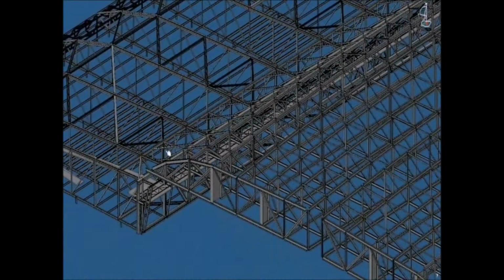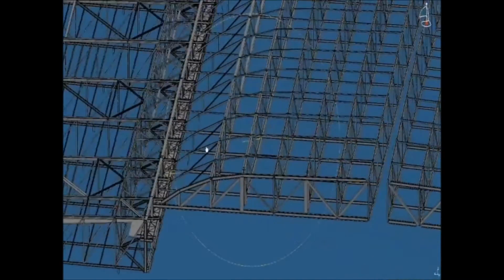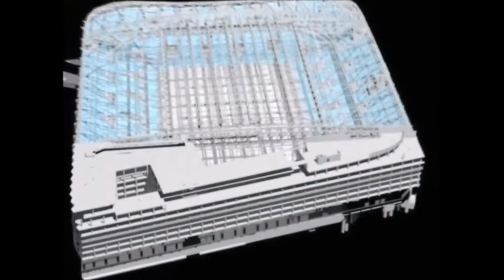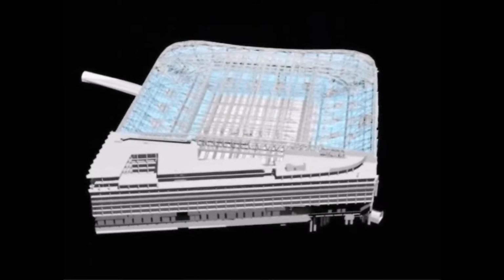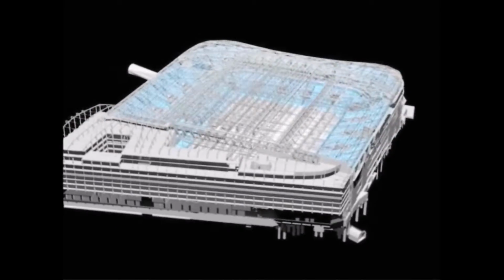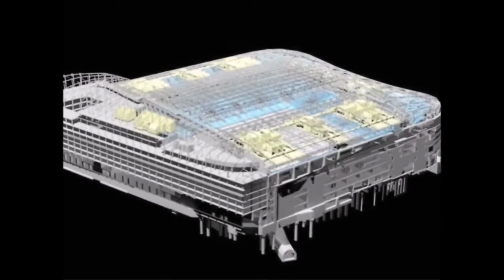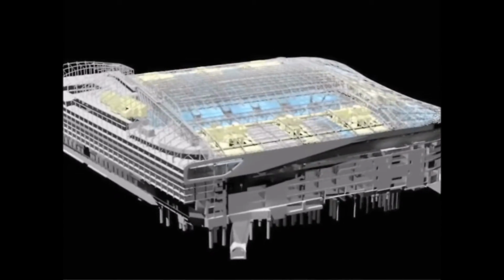We modeled the drawings made by the design office and integrated them into a 3D model to allow for the different analyses. For example, we made some corrections to ensure consistency between plans and cross-sections. We also carried out the analysis of the interfaces. In the case of the stadium, for example, we had air handling units in the roof with which we carried out the different analyses and made the adaptation to the structural element accordingly.